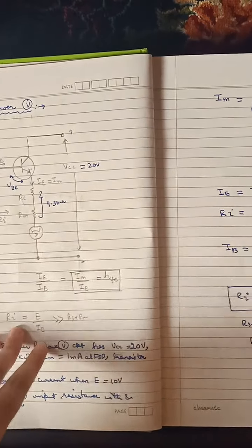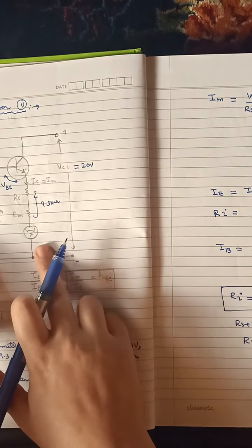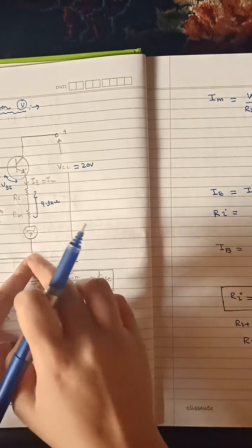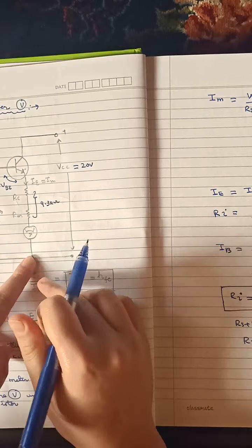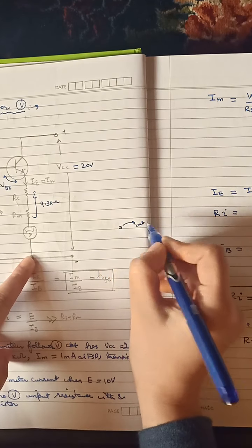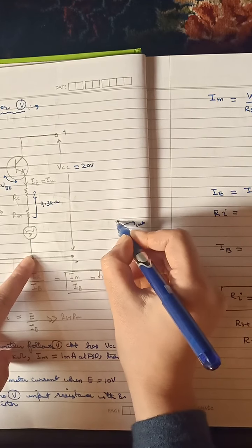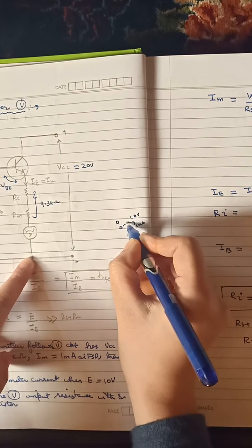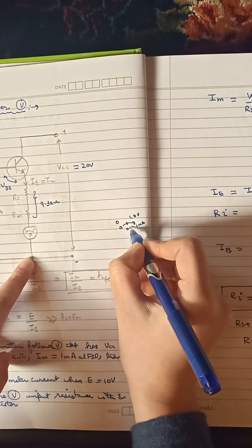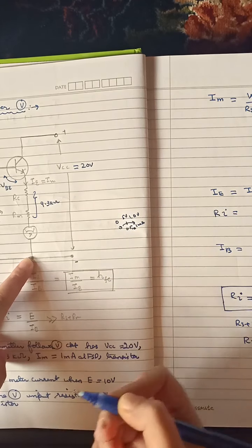How? Here, when we applied the input voltage equal to 10 volts, we had a current here of 1 milliampere, that means full scale deflection. So we can calibrate this meter from 0 to 1 milliampere, it is the ammeter, and for the voltmeter it will be calibrated from 0 to 10 volts. So at center it should be having what value here? When it is 0.5 milliamperes, then only it will show you the 5 volts.